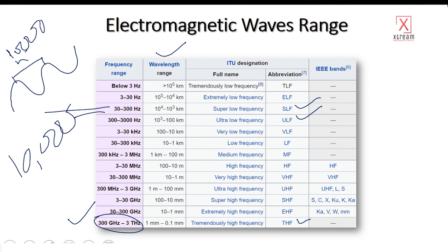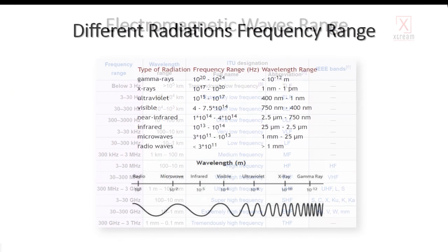We have also the IEEE bands over here. These are the IEEE bands which are managed by IEEE regulations. You can see also the C band and the KU band over here, and these are used in satellite communication. Like the C band, if you have seen a white LNBF on your dish antenna, it uses the C band, and also the KU band.